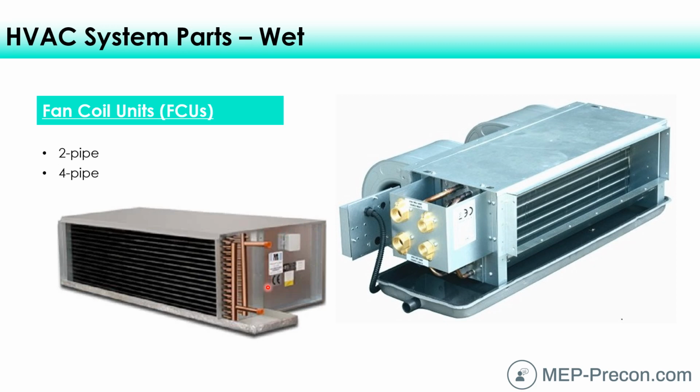You could have a 2-pipe fan coil, or you could have a 4-pipe fan coil. What are the differences, and what are the 2 pipes and what are the 4 pipes? Well, 2 pipes is supply and return, as you might have guessed. And so here's where we're going to supply either heating hot water at a high temperature, and we're going to give up the heat, and it's going to come back at a cooler temperature, or chilled water, which we provide at a pretty cold temperature. It's going to absorb heat, and it's going to come back at a higher temperature. So supply and return of either heating or cooling.